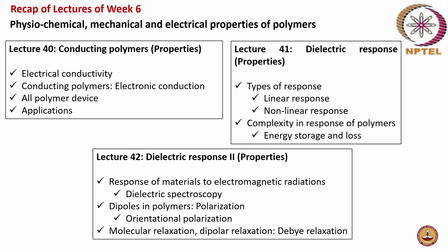So it's epsilon double prime and epsilon single prime. Yeah, so epsilon double prime, that is the dielectric loss, is on the y-axis, and the dielectric permittivity is plotted on the x-axis, and you will get semicircles. And in case of real polymers, you will get multiple semicircles due to multiple relaxation levels, right? Yes, ma'am. It's not actually semicircular, ma'am. It tends to be a semicircle. Yeah.